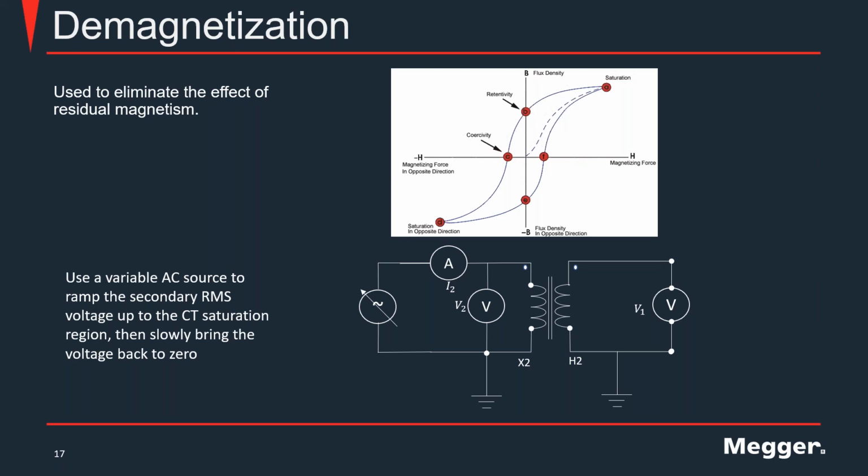In order to get rid of those effects, you have to perform certain connections depending on the configuration of the transformer you're testing. Typically on the other side of the transformer from where the CT is located, you have to short those windings. And depending on the configuration of the windings on the side of the CT you're testing, you need to make some arrangements. Typically, you have to jumper a couple bushings. Again, it depends on the configuration.